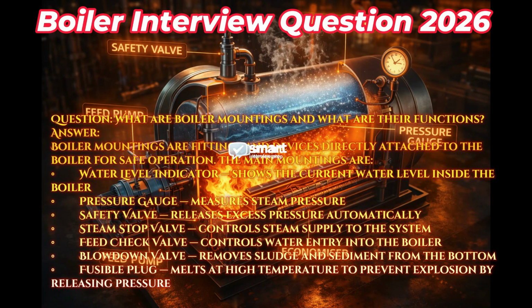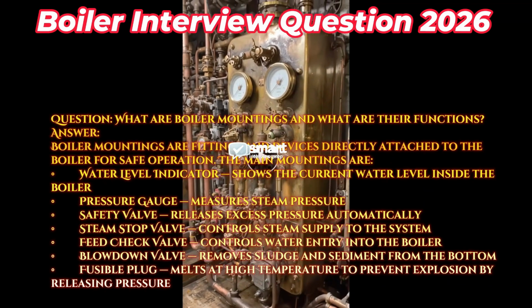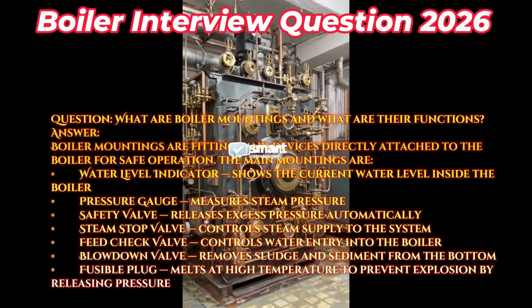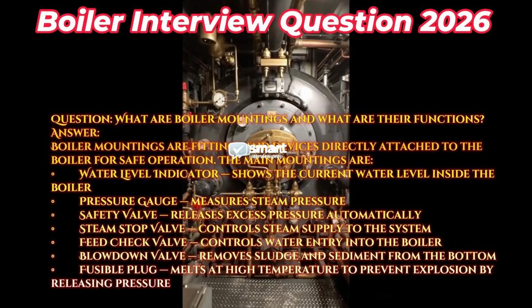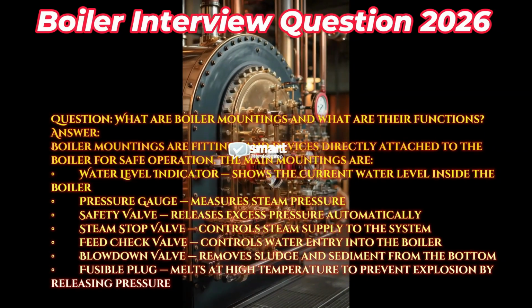Question: What are boiler mountings and what are their functions? Answer: Boiler mountings are fittings and devices directly attached to the boiler for safe operation. The main mountings are: a water level indicator, which shows the current water level inside the boiler. Pressure gauge measures steam pressure. Safety valve releases excess pressure automatically. A steam stop valve controls steam supply to the system.